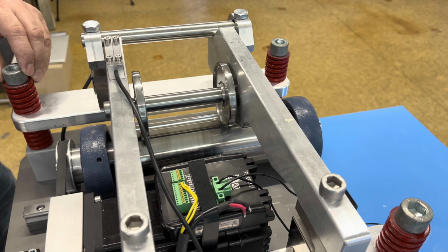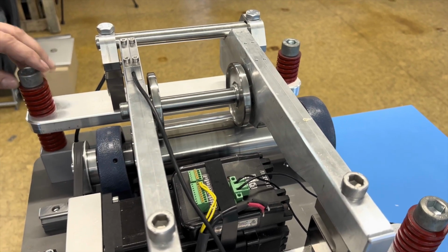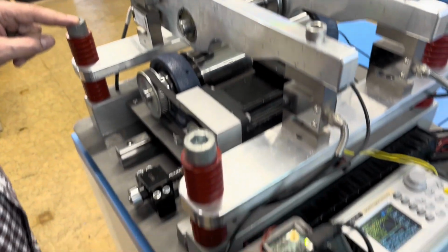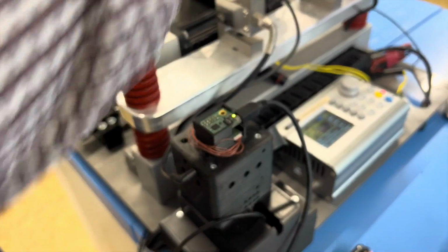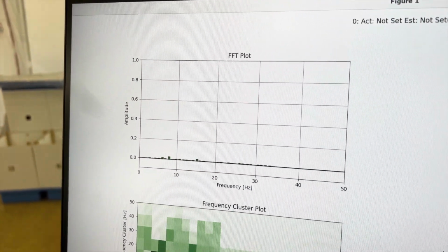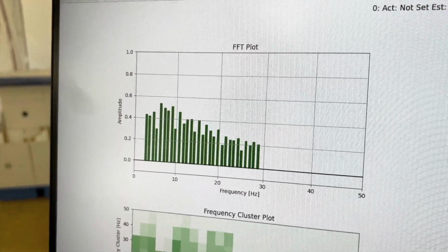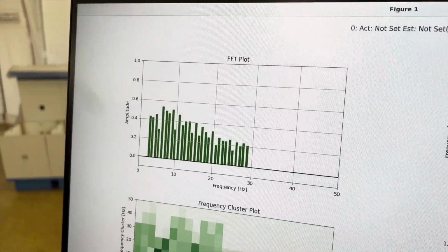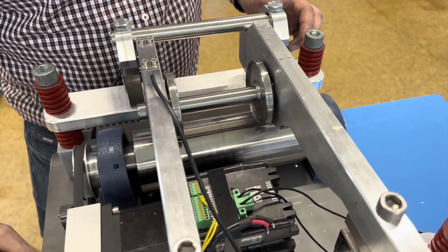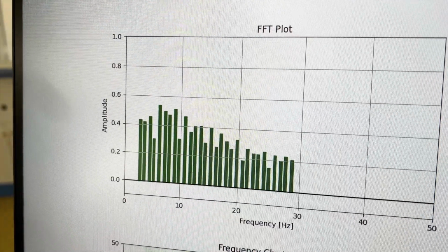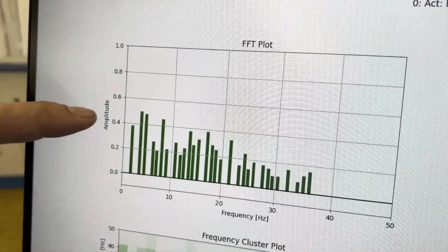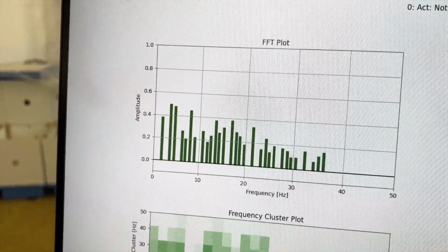Okay. Now we will go again from the sensor to our computing unit, back to the remote attestation, and you will then see over here the classification. Let's take a look at one more defect. Let's take a look at double faults. So here you see a double fault of different intensities and with a different amount of harmonics.